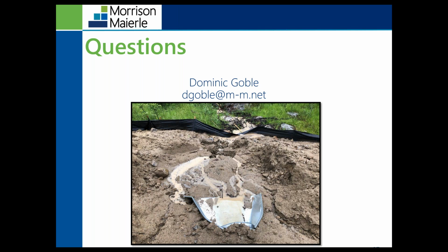So Dom, there's a number of folks that are listening in from Wyoming. Are there similar standards for Wyoming DEQ? Are you aware of what their requirements are, or where they might be able to look for that information? I'm not as familiar. I've had people in my class come from North Dakota and Wyoming. I don't believe that the state of Wyoming has the requirements of a certified SWPPP administrator. But the SWPPP administrator must still have knowledge of BMPs, have access to the site, and understand the construction. It's going to be similar.